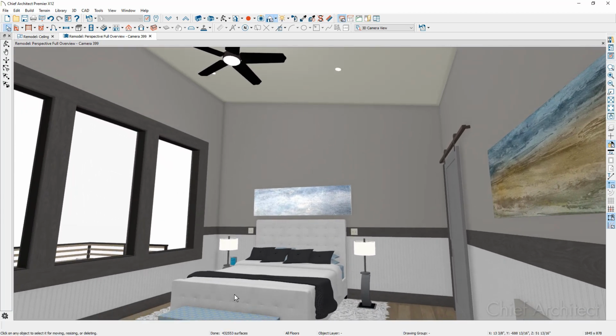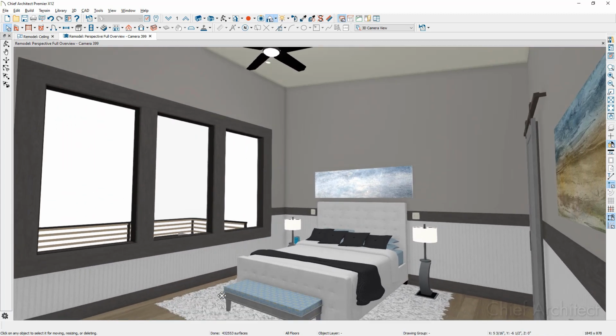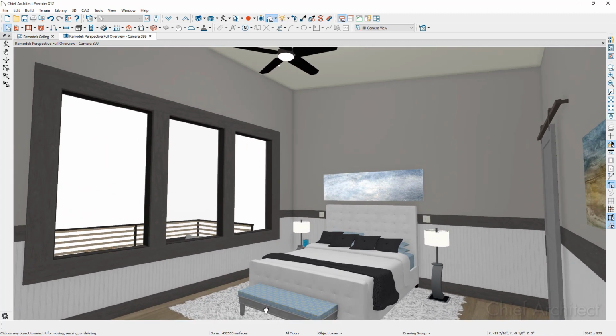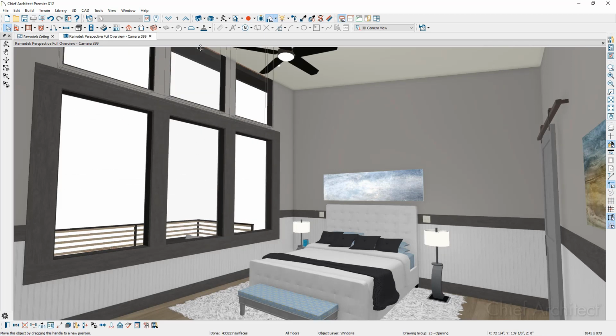And now I need to make some adjustments to the windows on here so we can maybe add some new windows above the existing windows in the design. I'm going to hold my Shift key down and select each of the 3 windows. I'm going to use the copy in the lower edit menu. I'm going to slide those up to the bottom of the beam. And then let's go ahead and open these up and make some adjustments in here.